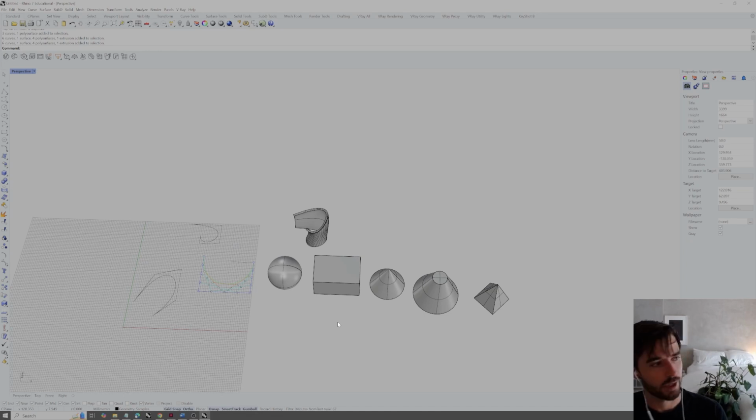A mesh, on the other hand, is going to be defined by a discrete number of, let's say, vertices. So a mesh is defined by points in space and the connections of those points, which is very similar to our polyline. So you can think of a mesh as a polyline type of geometry, and these polysurfaces are more like this NURBs or Bezier type of geometry that are calculated mathematically.